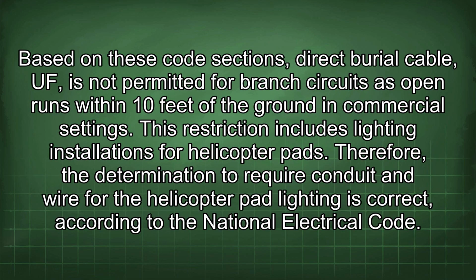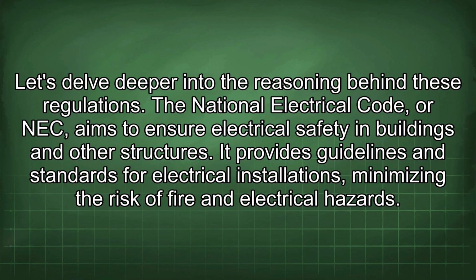Based on these code sections, direct burial cable (UF) is not permitted for branch circuits as open runs within 10 feet of the ground in commercial settings. This restriction includes lighting installations for helicopter pads. Therefore, the determination to require conduit and wire for the helicopter pad lighting is correct according to the National Electrical Code. Let's delve deeper into the reasoning behind these regulations.